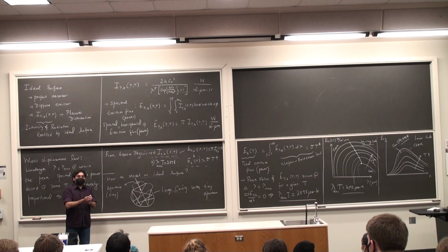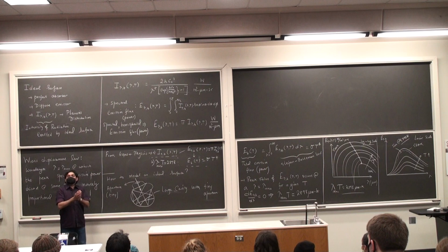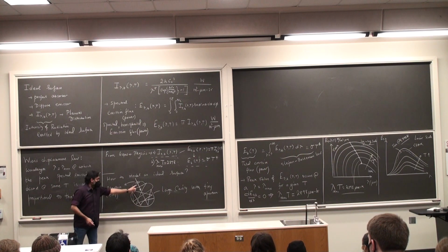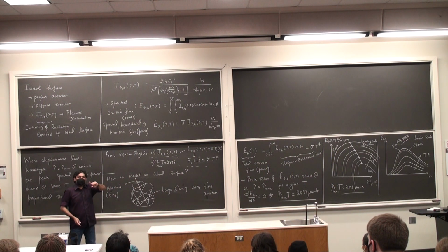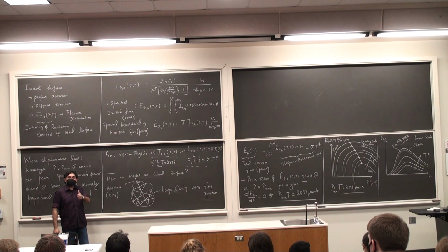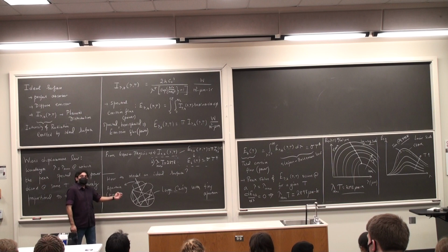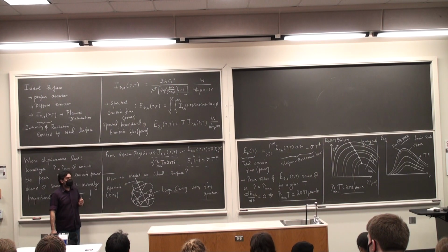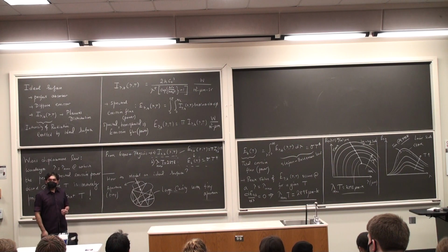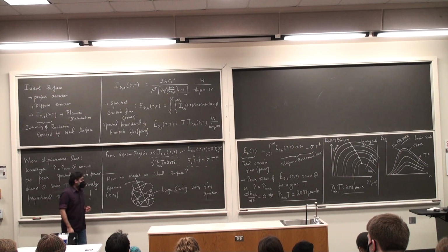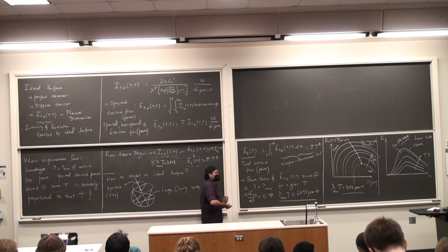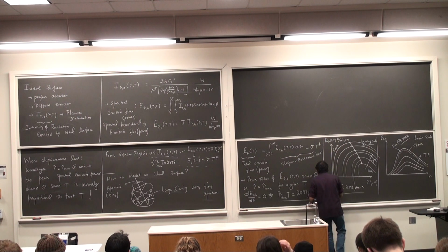And so if one of these rays escapes out of the aperture, it is going to be completely diffuse because it is independent of direction. As a result, this aperture will act as a diffuse emitter. Once again, this is an approximation, an idealization of an ideal surface. Within certain limits, this seems to reasonably work. Okay? Alright, so that's how you create an ideal surface.